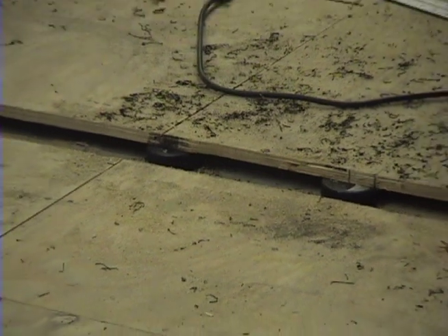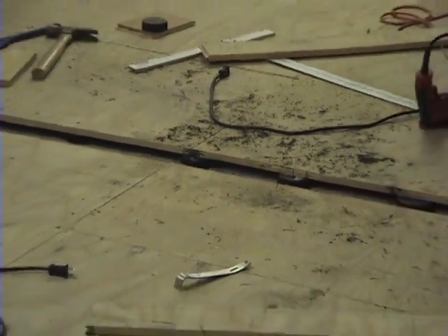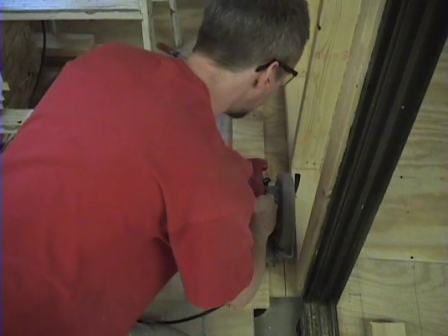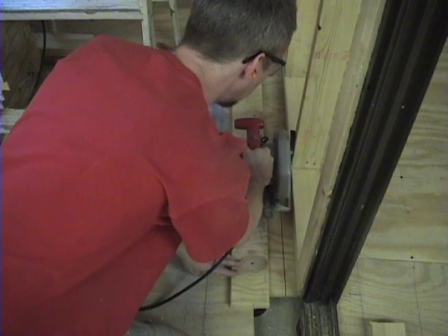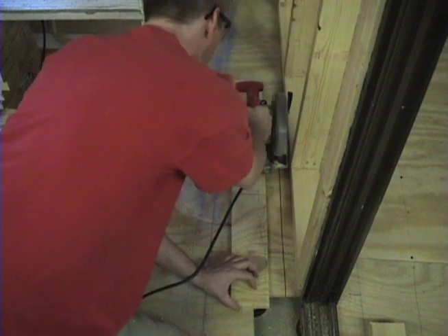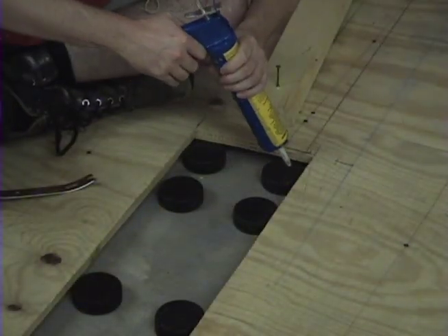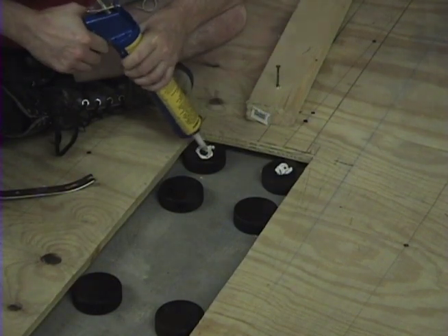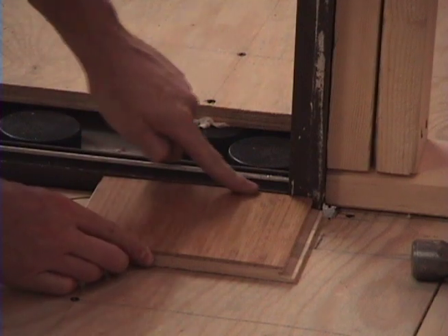Since we are in the mode of cutting the subfloor, it pays to take this opportunity to cut the subfloor between your control room and the adjacent room to provide isolation between the 2 rooms. We are following standard double wall construction techniques, so using the circular saw and cutting the subfloor gives 1/8 of an inch of airspace between both rooms to prevent acoustic short-circuiting. Once the cut is made, then we can put more pucks down and place a bit of glue on them to fasten them to the door. Pop the door in the trench and fasten it to the wall. Now notice that when we put in the finished floor, the threshold will be flush.